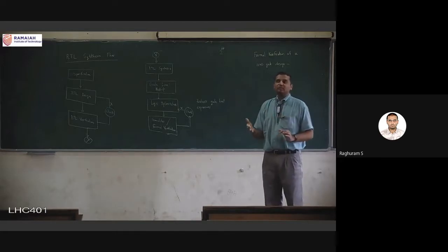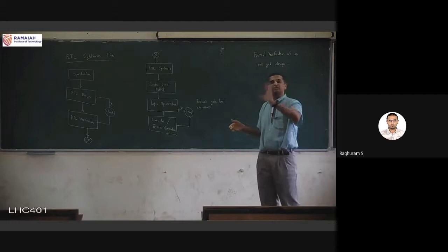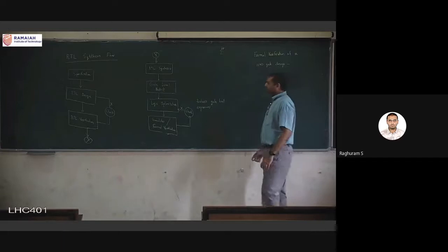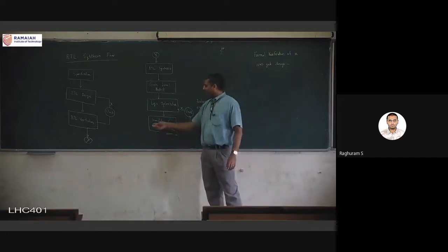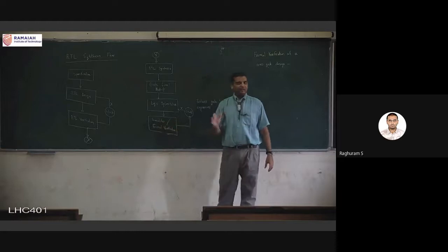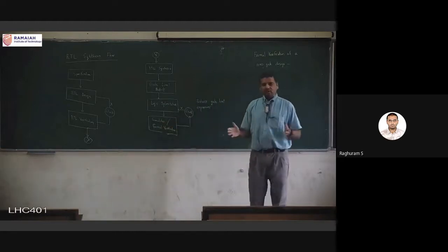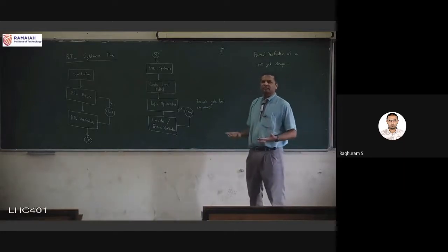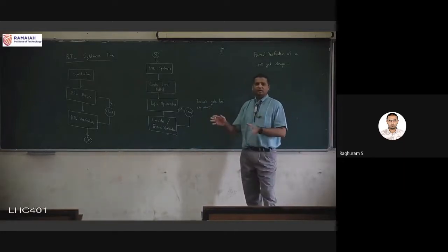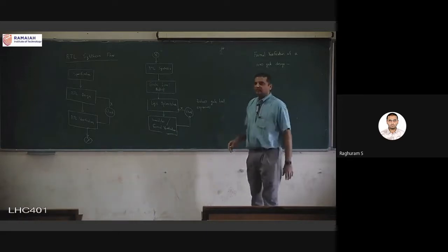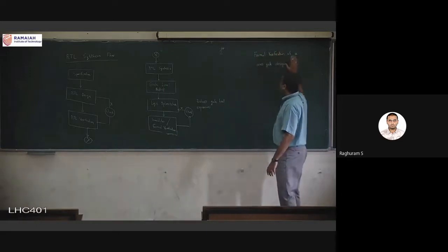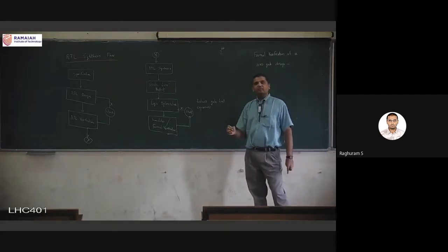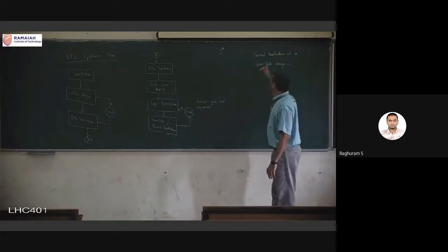So the question comes, what about the order? If after this input I give this input, will the circuit malfunction? Questions like these are very difficult to answer with simulation. Generally, they won't cause a problem. If you have an ordinary block that is not so critical, you can live with it. Even if it causes a problem, it might get overshadowed by some other computation. But if you have something at the heart of your design, formal verification is better.